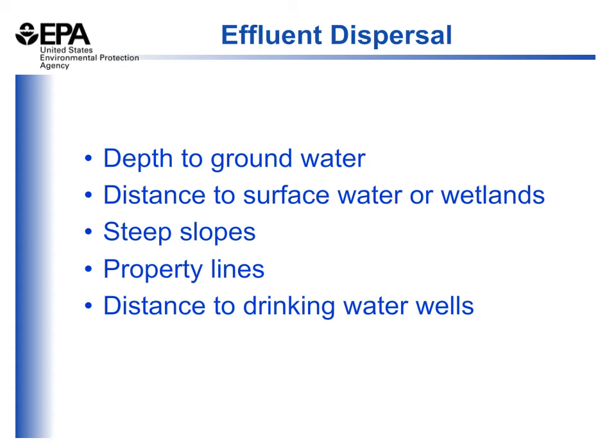When you're looking at the depth to water, you want to make sure you're looking at the maximum water level. Groundwater levels can fluctuate significantly on a seasonal basis, and this varies from place to place within the country. Depth to high groundwater can be determined by conducting the measurements and digging your test pit during the high water period of the year, typically in the spring months of April or May. And again, that will vary in different locations around the country.